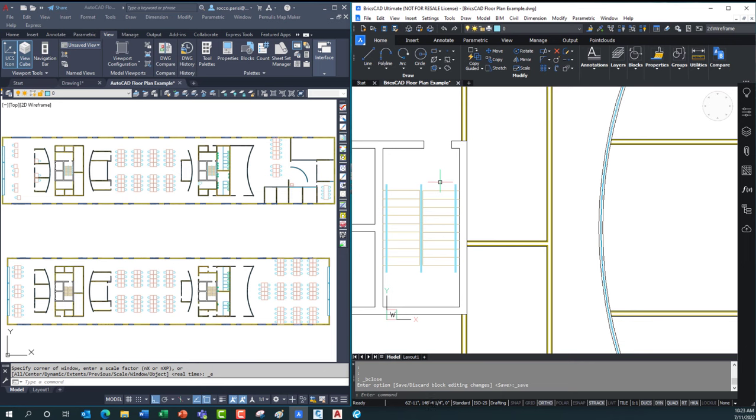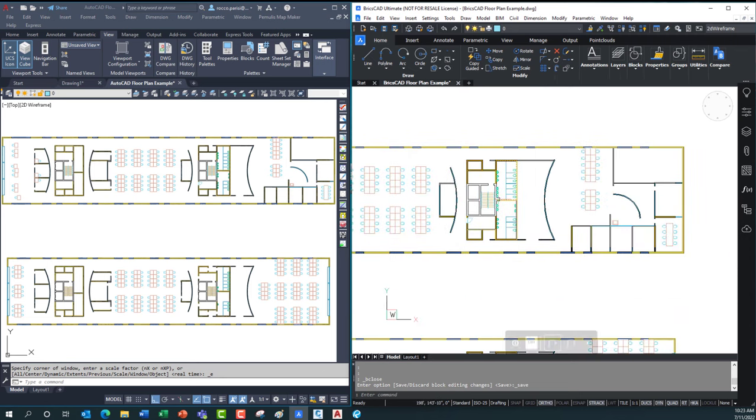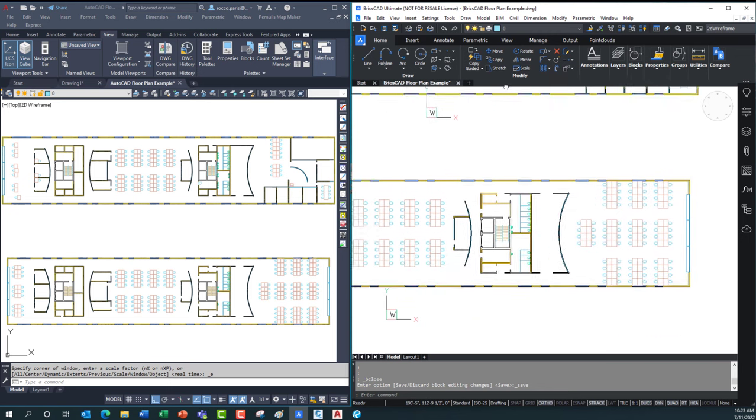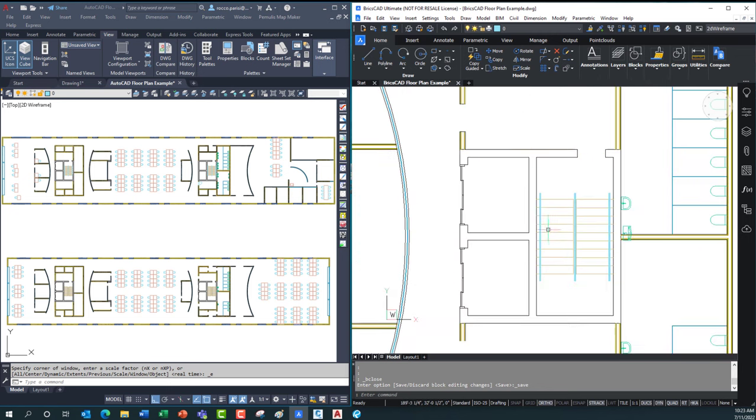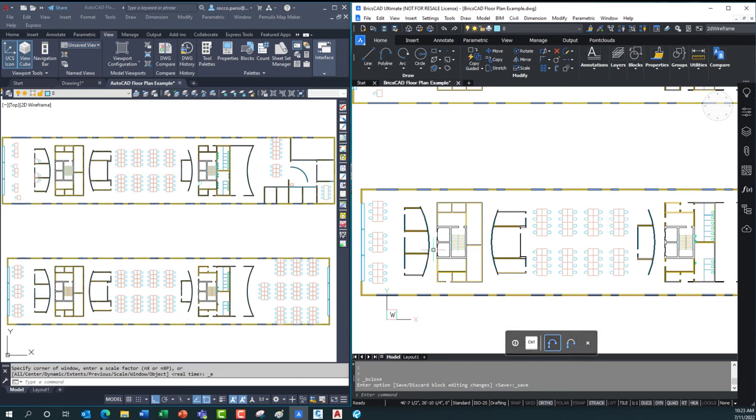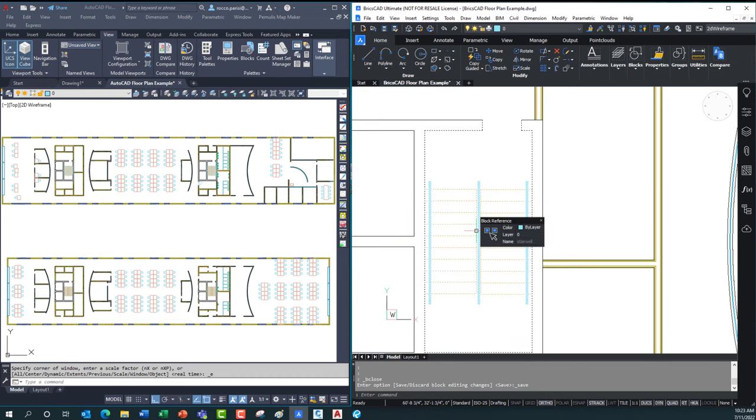All right. This stairwell now looks fine. But what about all the other ones? Well, remember, blockify converted those to blocks, unnamed blocks. All the other stairwells have now all been updated that quickly. In just a couple of seconds, you can convert any type of graphic presentation on your floor plans into a block using that blockify tool, modify it, and move on.